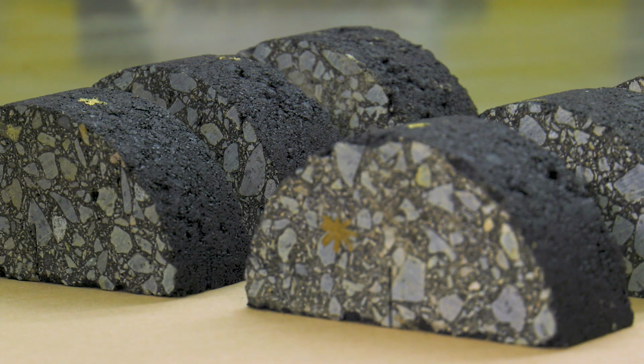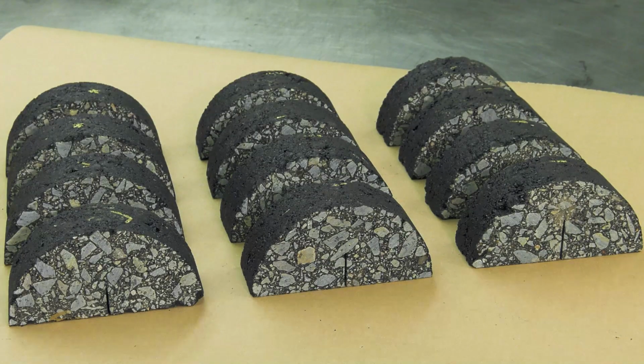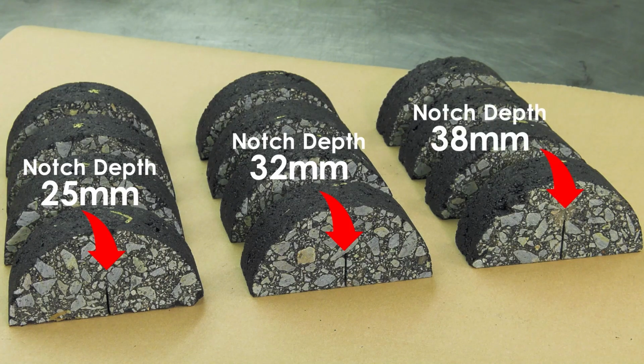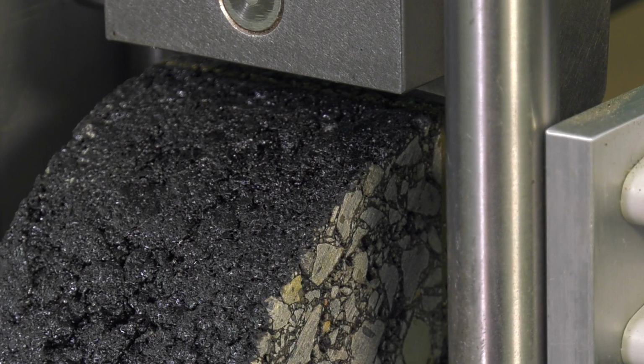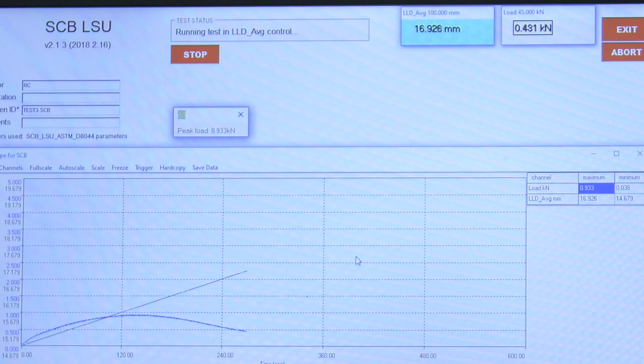The SCB test uses a half-disc test specimen with different notch depths cut parallel to the loading and vertical axis. The notch depths are 25 mm, 32 mm, and 38 mm. Load is applied along the SCB specimen's vertical radius, and the load and load line displacement, or LLD, are measured during the entire duration of the test. The load is applied in a way to maintain a constant LLD rate of 0.5 mm per minute for the duration of the test.